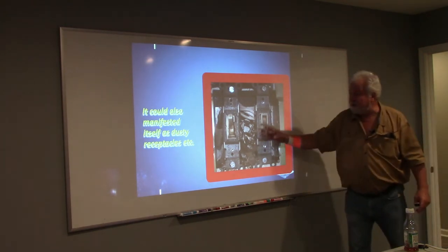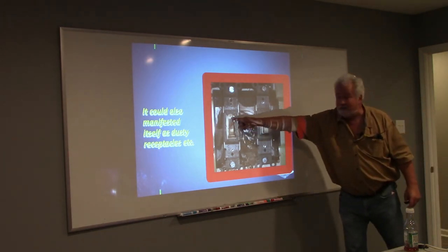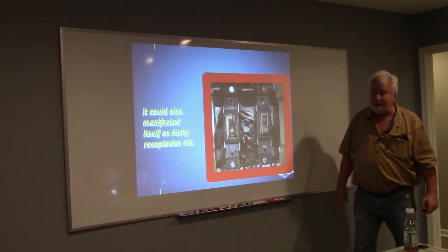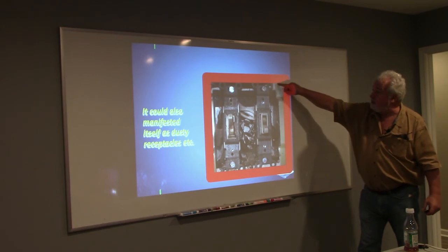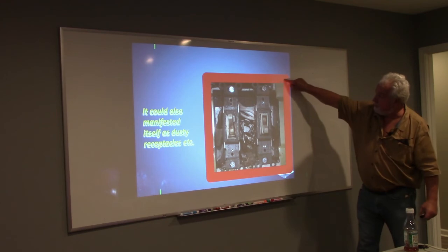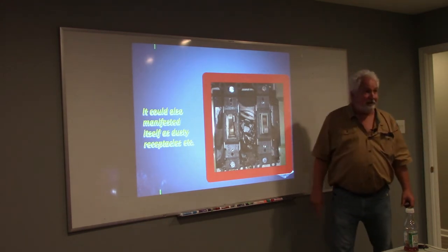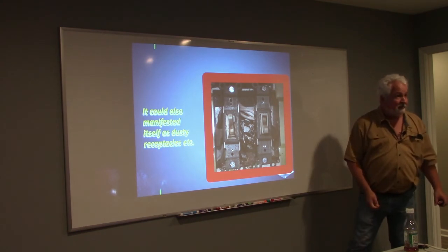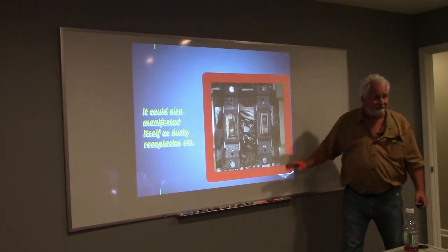If I see a lot of dust inside it, or it gets really grimy like this, that's telling you dust is going across it on a regular basis. You may even see it on the receptacle cover. If I'm seeing it like this on the receptacle cover, that's telling me it's gone negative. It's sucking dust into the room.